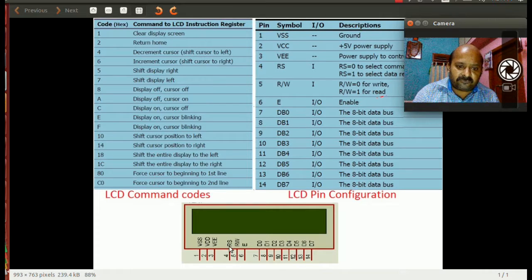If you see on the left hand side, there is a pin called RS. RS basically stands for register select mode. There are two different modes: one is the command mode and another is the data mode. What is the difference between these two? Say, if you want to use an LCD panel, then there are some initializations that have to be done, or specific instructions that have to be given to the LCD panel which are not the data.